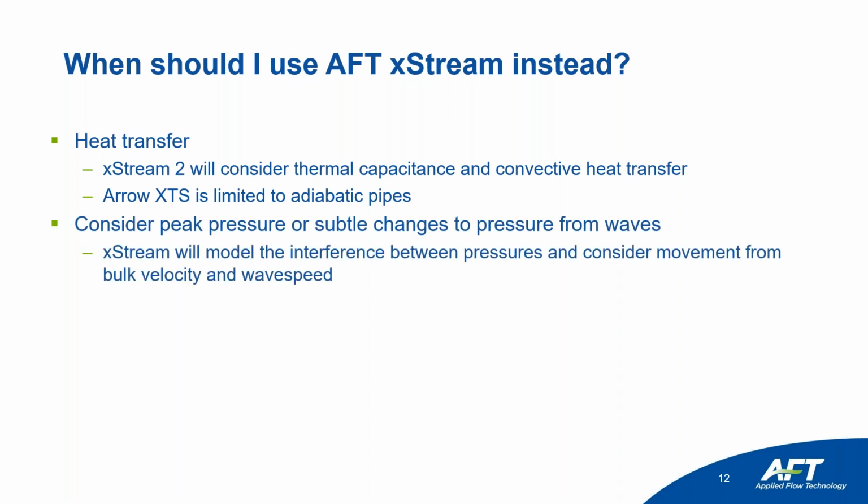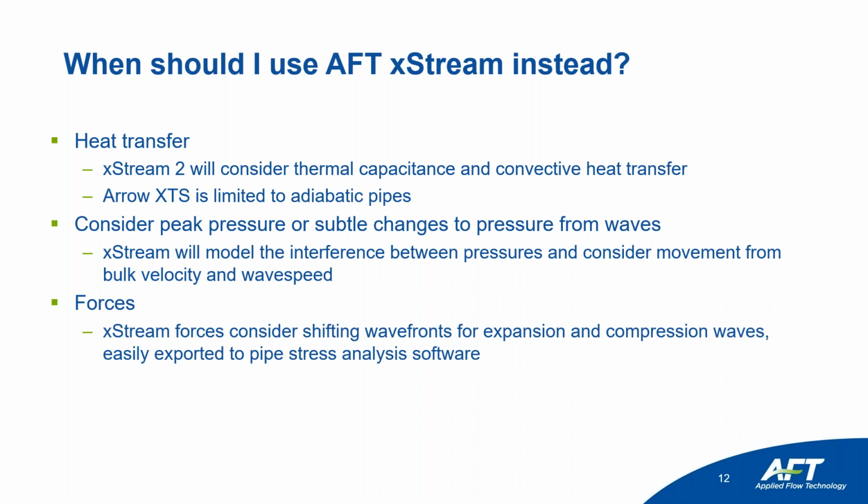xStream will consider things like your peak pressure or really subtle changes to pressure from different waves. So it can consider things like interference. If you have a relief valve open in one case and it drops the pressure, or if one relief valve fails and it slams closed and causes another high pressure wave, that might trigger a different relief valve. Again, it'll try to capture that interaction because we're cutting the pipe into so many different smaller sections. We can see how those pressures and flow rates change throughout the system. Finally, because we can more precisely capture those pressures and flow rates, we can also consider forces.